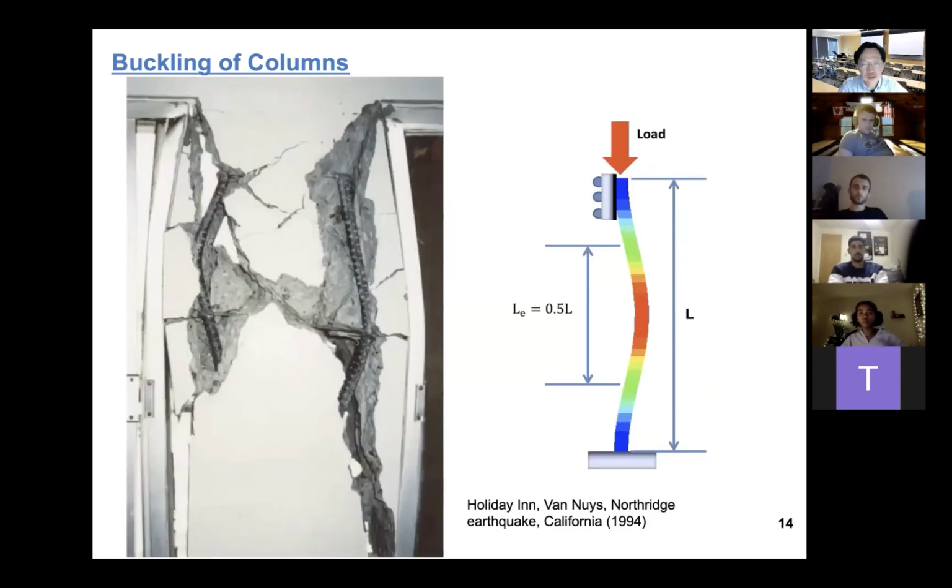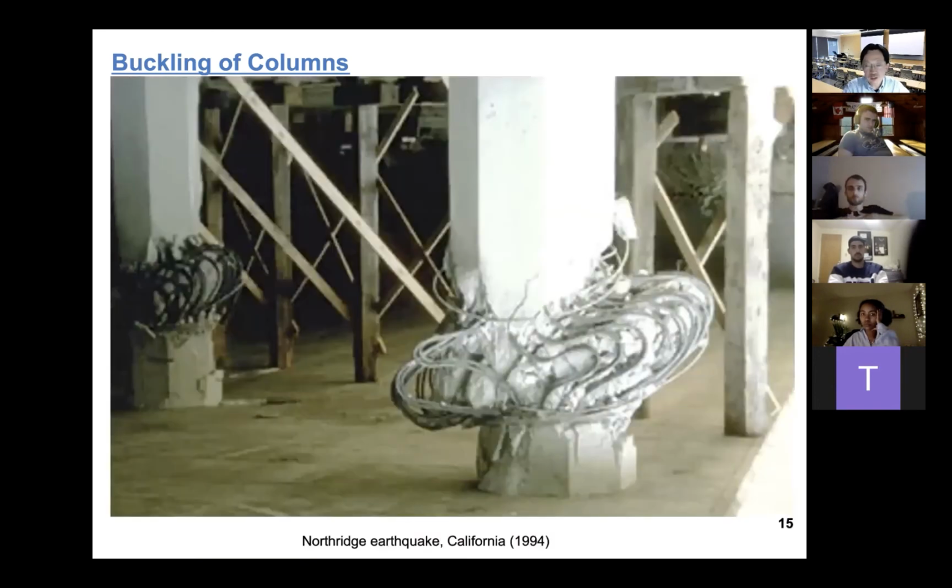Now, from the steel design, you have learned the different boundary conditions and use what we call the effective length, and that's what we're going to talk about today. How do we calculate this effective length from theory? From steel design, you've been provided with a table, right? And from the table, it tells you that there's an effective length coefficient, the capital K, and by multiplying this, you can just calculate it. But you need to know why these values are sometimes 0.5, sometimes 0.7, sometimes 0.85. That's what we want to cover here.